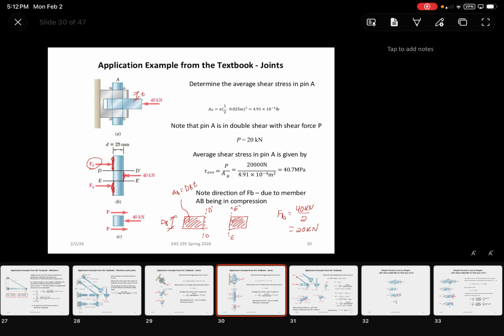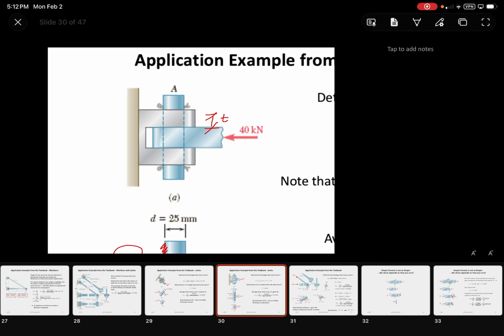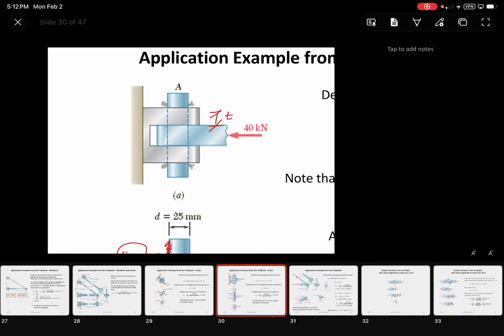Yes. I'm just a little bit confused with the drawing. So where on the pin is the bearing force or bearing stress actually taking place? It's occurring both on the plate and the pin. So if we take a look at this drawing, for example, you have a compressive force basically applied right there. So that means that you are going to have bearing from the bolt. Okay, I see it now. Yeah. Now, vice versa, you're going to have the plate equal and opposite force. I don't know what plane it would have been on. Yeah. So bearing is basically occurring on those three planes.